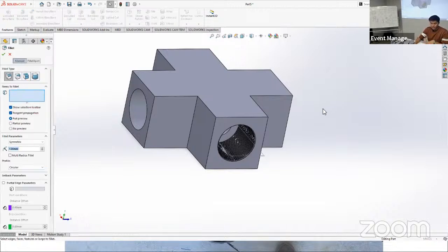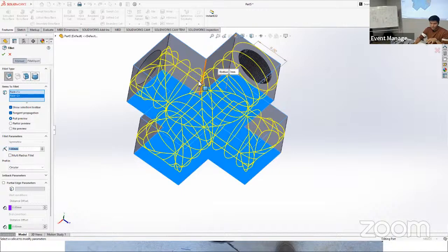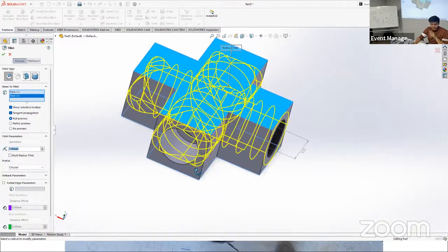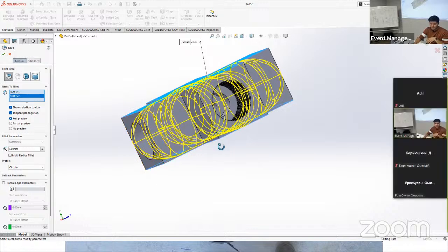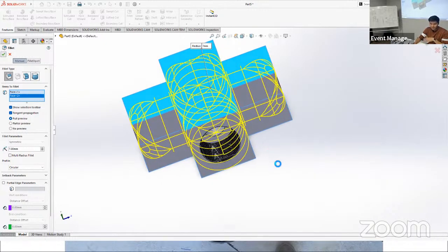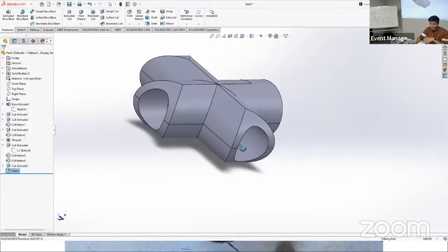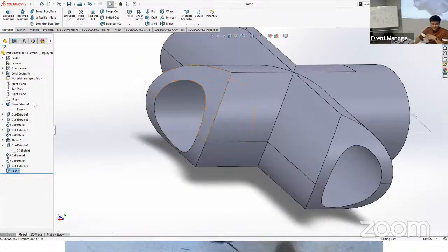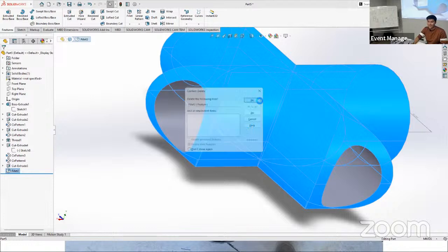Actually, we can make it another way this time. So it's again 7 millimeters, but we can just click the top one and the bottom. But that gives us a preview that these corners are going to be filleted too, which is not going to help us, because if I just accept that, okay, it gives us this weird shape for our bolt, so it's not going to work. That's what you should consider when designing. So that's why we made our last mistake.